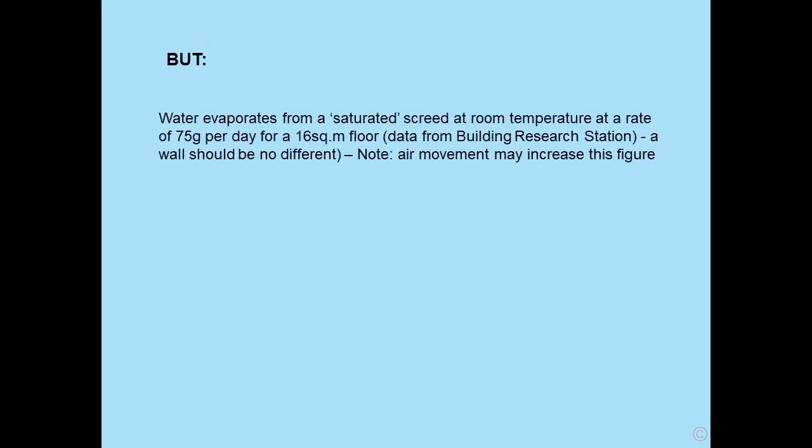However, water evaporates from a saturated screed, remember he's talking about the floor, at room temperature at a rate of 75 grams per day for a 16 square metre floor. That's data from the Building Research Station. And in reality, a wall should be no different.